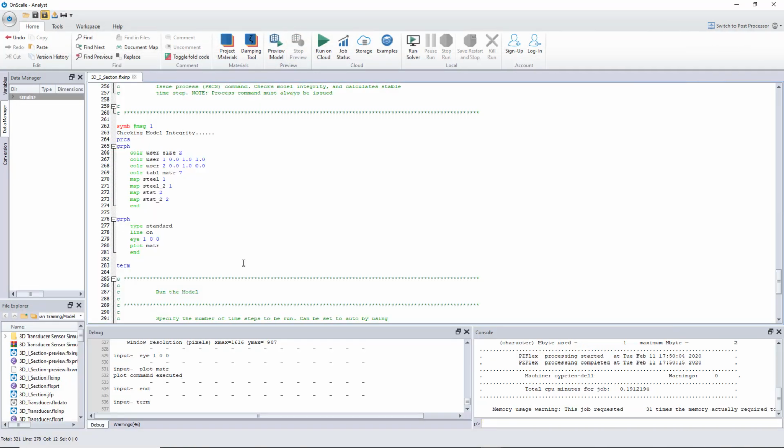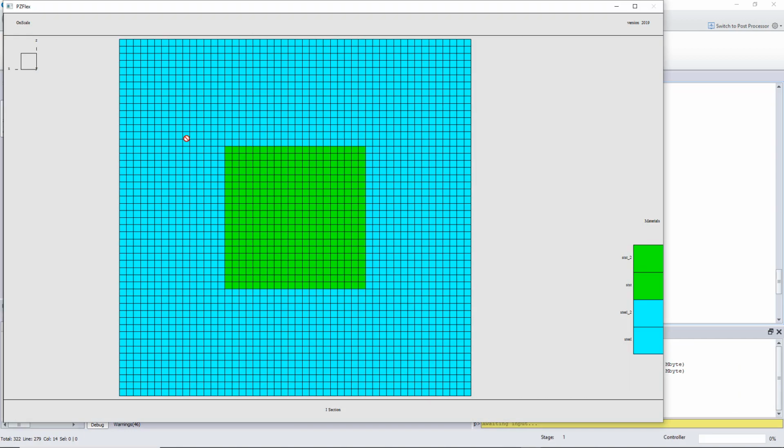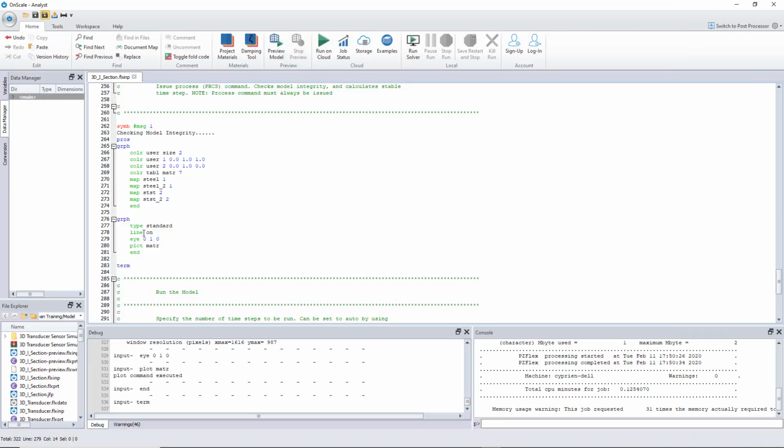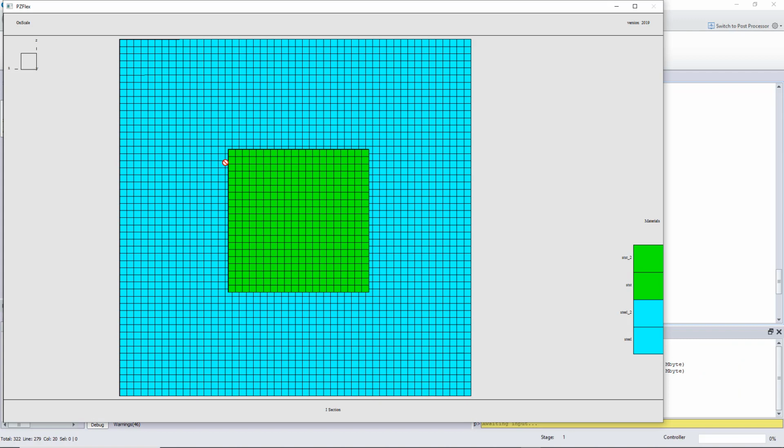If now I want to visualize from the rear of the model, looking at the y-axis, I just preview that, and I see it from this side. So it looks like a plate, a 2D plate. That's why sometimes, if you want to make screen captures, it's better to add 0.01, a very small offset. Like that, it looks a bit 3D. It doesn't look like a plate.